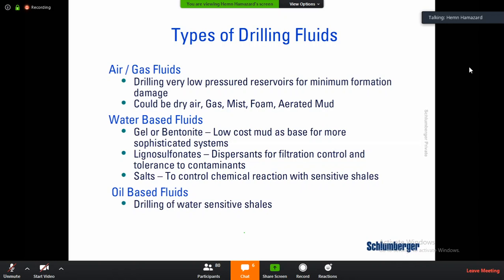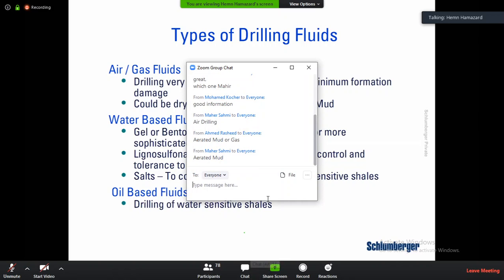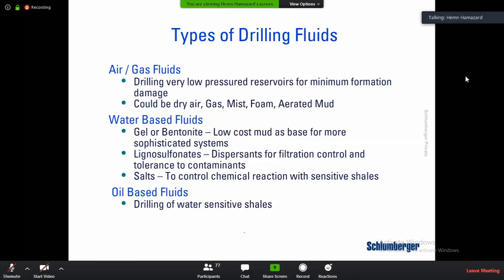In HKN, we are using a lot of KCl in our mud. Apart from using KCl to raise the mud weight and stuff like that, it also prevents shale reactivity. With salts, NaCl or KCl, we add them to the chemical mix mainly for shale inhibition, shale prevention.